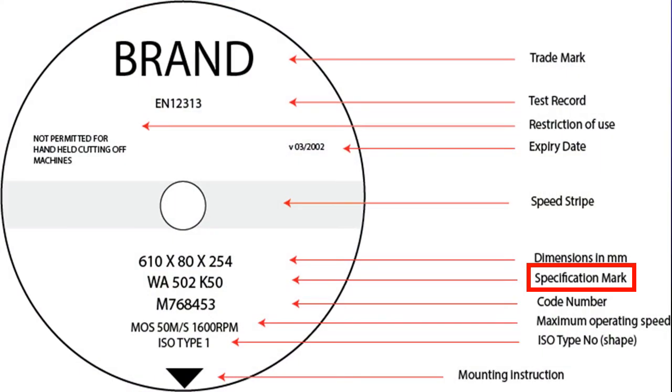These parameters can be consistently designated in a standard grinding wheel marking system defined by standard organizations. This marking system uses numbers and letters to specify the abrasive type, the grit size, the grade, the structure, and the bond material.